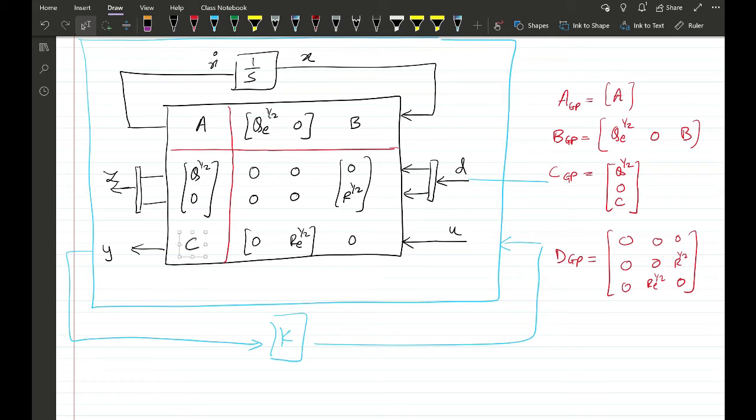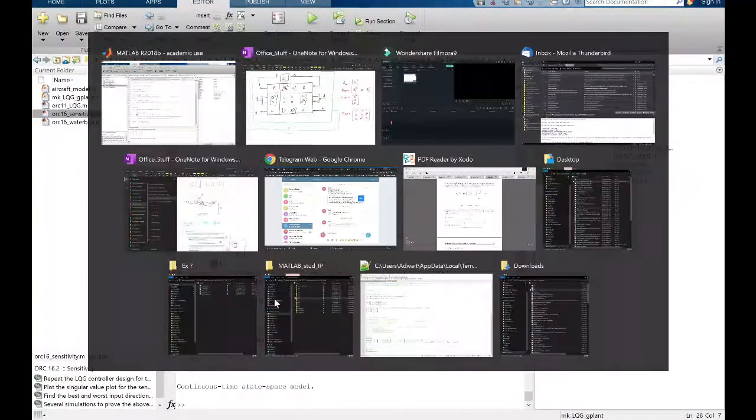Also, one more reason why this is not a problem is because the disturbance D that is entering the output or the measurement is zero mean, so in expectation that averages out, and the negative sign here does not change anything for the closed loop especially.